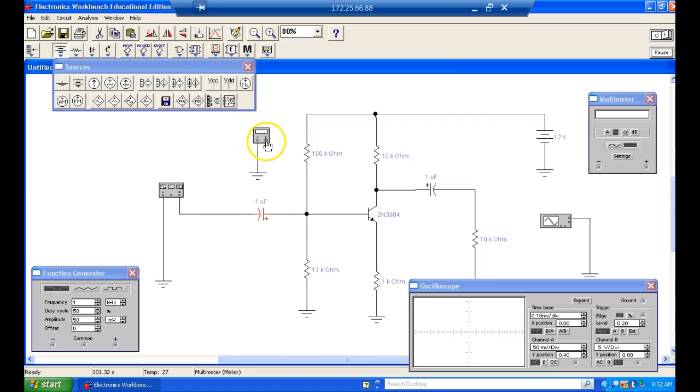Let's see this. So it's measuring what? Yeah. So my input bias voltage now is, I'm sorry, it's going to make it go way down because it's seeing this as 100 ohms. It's seeing this at 0. So now that 100 ohm resistor is setting my bias voltage.